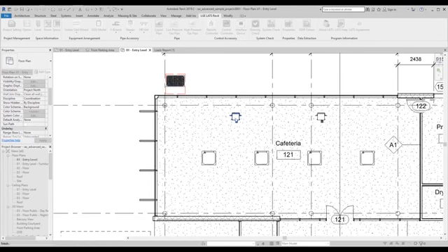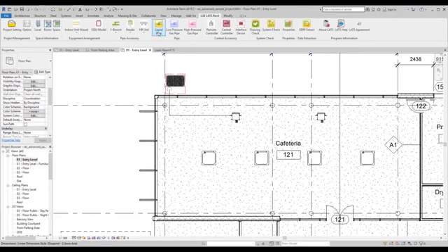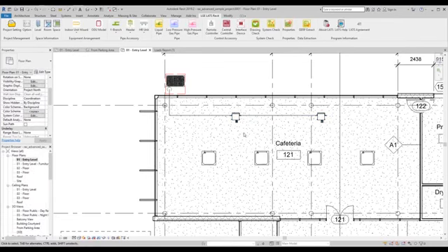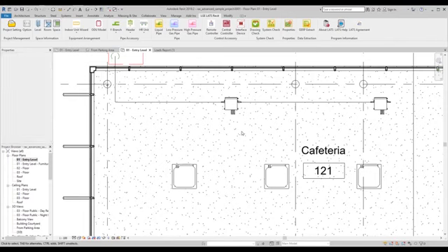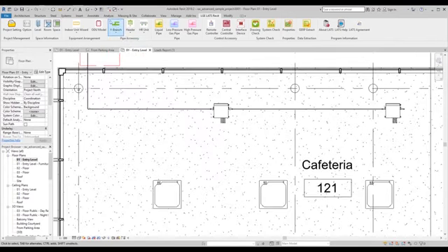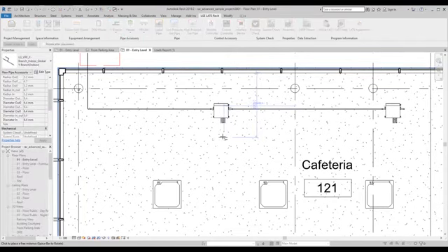You can automatically connect the liquid pipes between the ODU and HR units by clicking Liquid Pipe and selecting the 2 units you want to connect. The left-hand HR unit will serve the 2 IDUs on the left. You can use a Y branch to connect 2 indoor units to a single port on the HR unit.